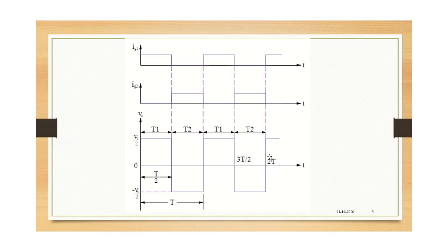applications. Okay, so if you want to go for very high power applications, then the AC what you should be expecting should be sinusoidal. To get the smooth sinusoidal curve, obviously we know we have to go for a filter circuit to remove the harmonics in this output what we have here, right?